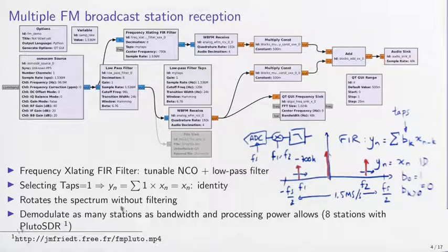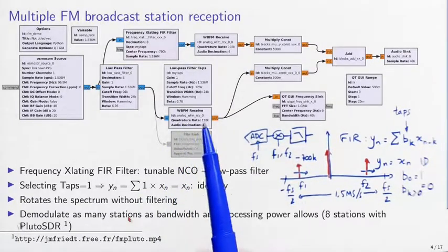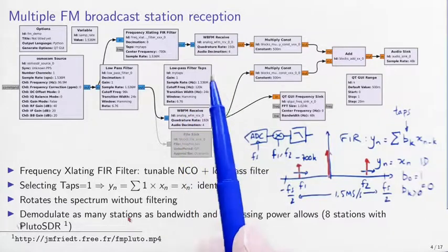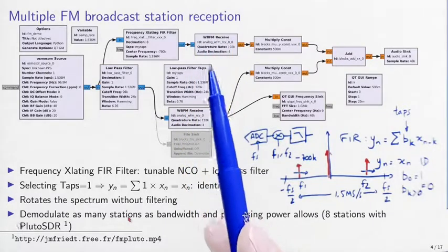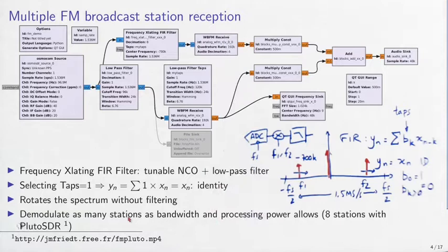Now this capability will be limited by the bandwidth. The number of stations found is defined by the sampling frequency fs and hence the bandwidth that we have acquired. The wider the bandwidth, the more samples to be processed, the more computational power is needed. And furthermore, we can only analyze as many channels as we have central processing units. So at some point, if we have too many of these wideband FM receivers, we will run out of computational power.